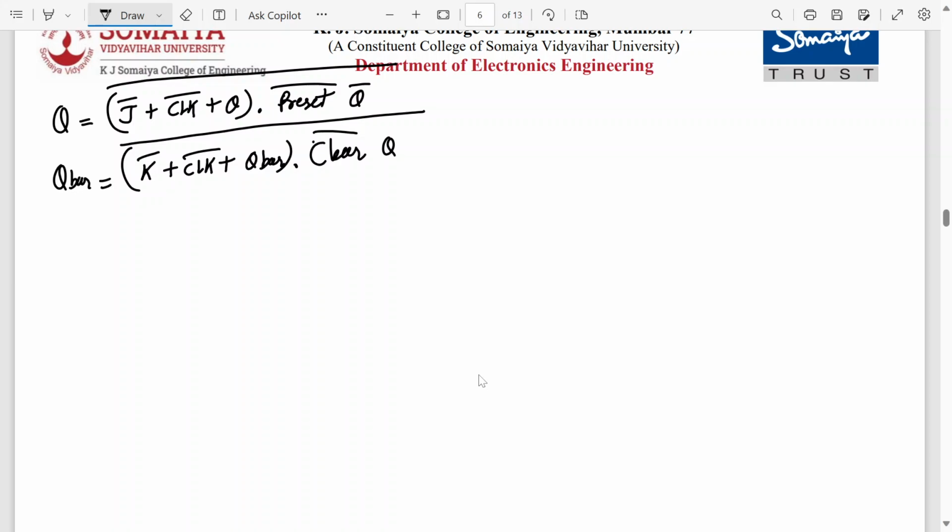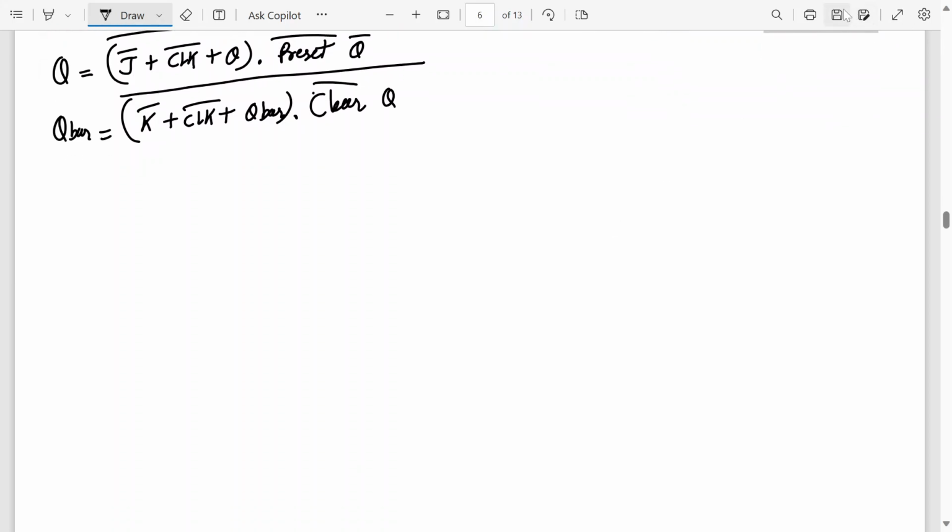Okay, so let's start building the network, static CMOS logic. So here it will be 3 transistors in parallel. Connect them together. My inputs are J bar, clock bar, right? And this will be Q, right?